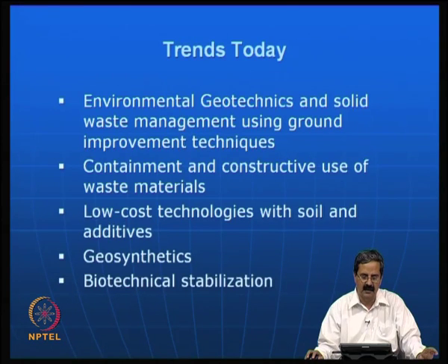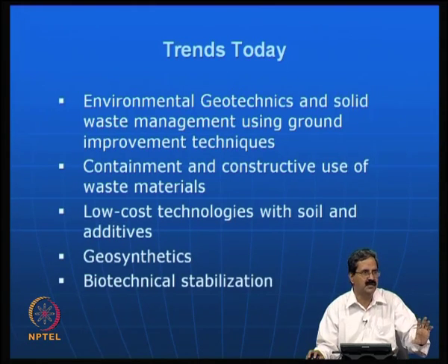There is a lot of work that has been done in the construction of structures using waste materials. Then low cost technologies with soil and additives, as I just mentioned. In fact, in terms of science, we have application of science and technology for rural areas, where instead of concrete blocks for houses, you can go for soil cement blocks, which are quite efficient, and burning needs to be avoided, like burning of bricks. In burning of bricks you are spending energy. You do not need to burn, because why you are burning the brick is you want to get some strength of the brick. Essentially you are trying to dry out the moisture and press it in some form, so you will get some strength. The same strength if you can get from compaction, it is fine, is it not?